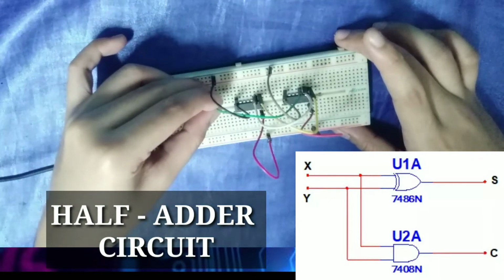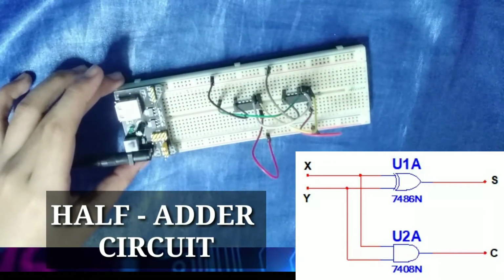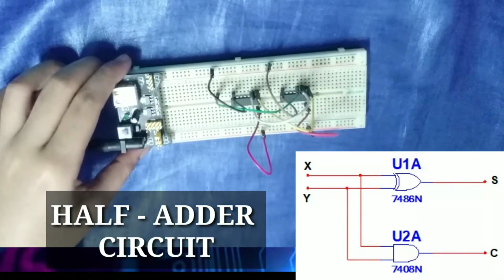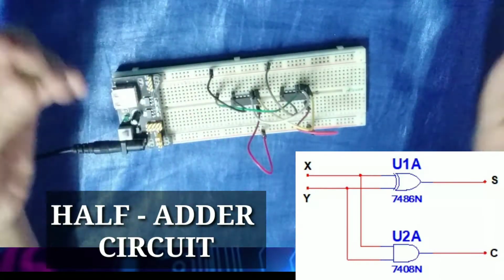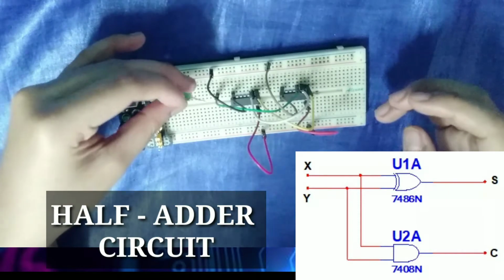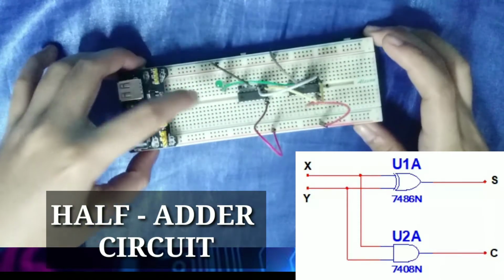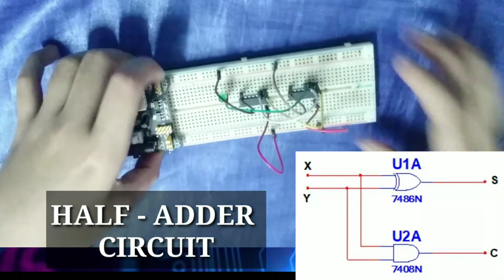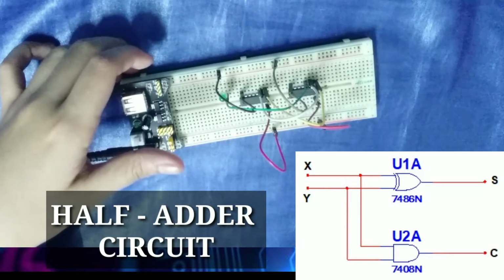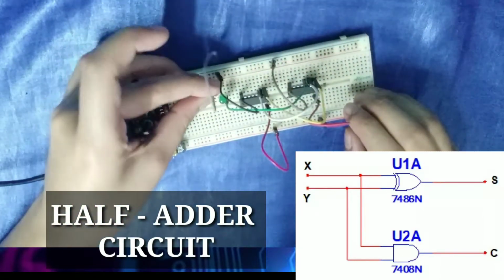Okay, so let's put it here, and we will also be considering the output for the sum. Since the wire is color green, let's just put a green wire here. This green LED will be the output for our sum from the XOR gate. And let's ground our LED here.